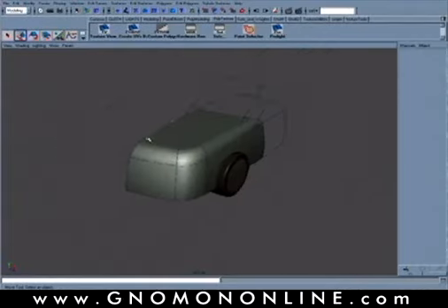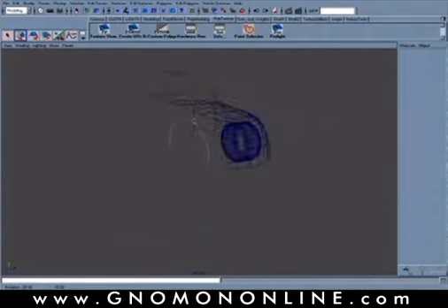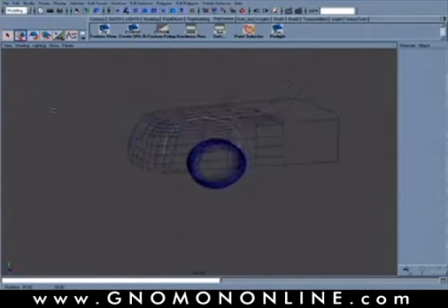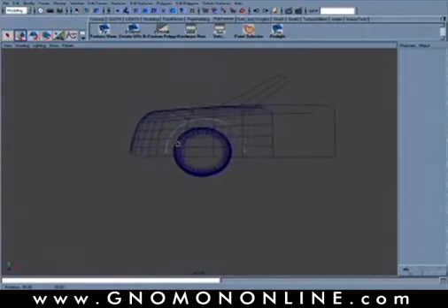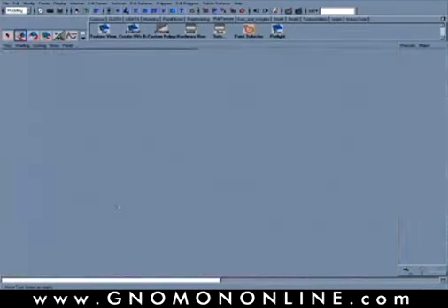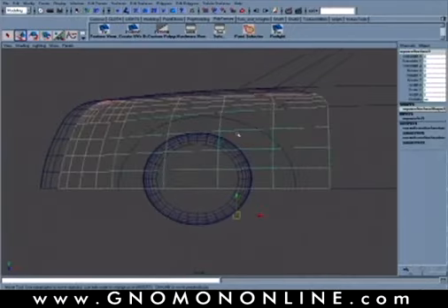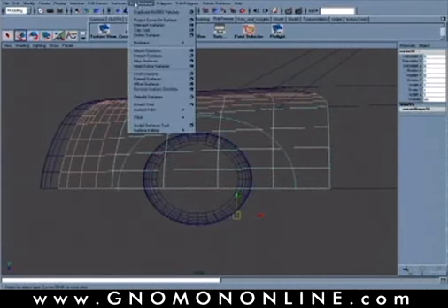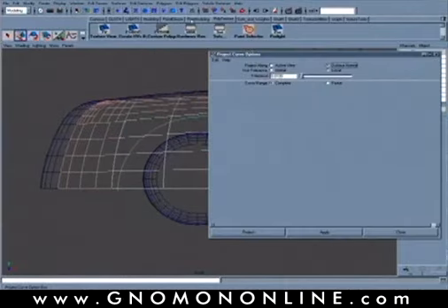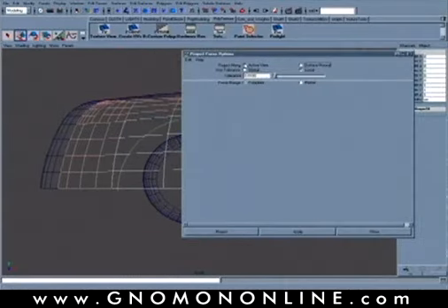So notice that that part is sitting in the middle of the curve, or the middle of our center line here. So we don't really need to adapt this one over to the edge because we can just project it from our orthographic view. So what I'll do at this point is go in here and select my quarter panel piece, select my curve here, and then go in and project the curve on surface. Okay, using the reset options of what's called active view. So we're actually just projecting it all the way through that orthographic active view now. And then we'll hit the apply.